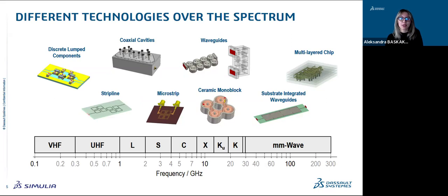Depending on the operating frequency and device specification, different technologies for filter design may be used. For lower frequencies, it is fine to use filters, for example, on SMD components. But for high frequencies and small losses, waveguide technology has to be used. The design and analysis of such devices can be challenging, and simulation can play a vital part in the development process.